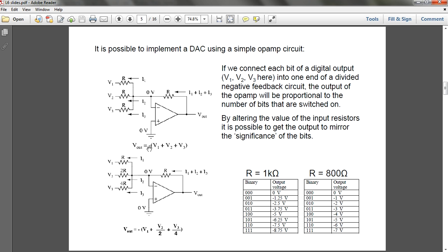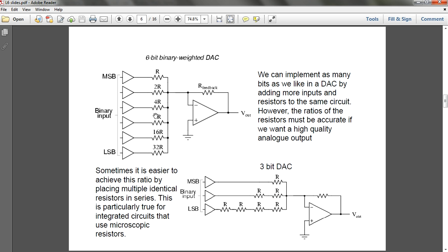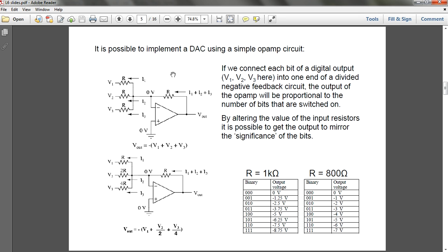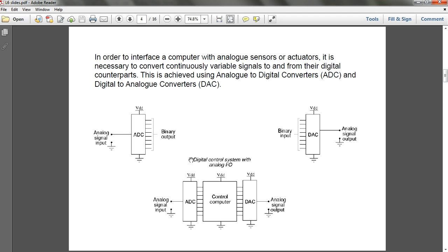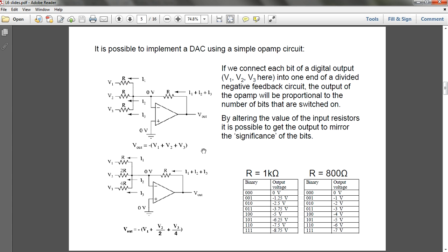So it's whether you want it to be inverted signal or non-inverted signal. It all depends on how you want to connect it. It is simply the case because the DACs in this scenario are all connected in inverting. As you can see in the notes, they are connected in the inverting side. However, you only have a negative output. You have a negative gain in a certain sense.